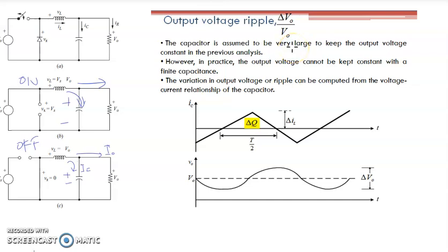So if you take a look at the capacitor or at the output voltage Vout, when the capacitor is charging and discharging, how is the response at the output load terminal? By right, the average output should be stabilized at this expected voltage level, but that is ideal. Practically there will be a swing in terms of ripple, delta Vout, minimum and maximum.